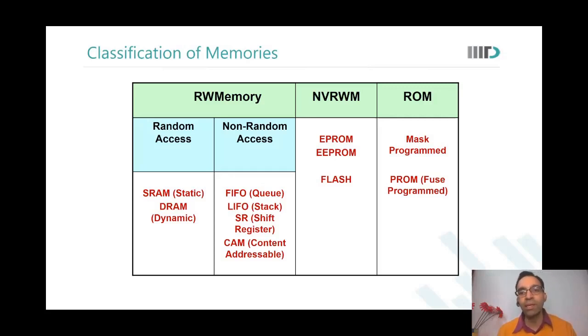This is the queuing mechanism which you would use for clock synchronization across two different domains. So how big a FIFO would you need? Sir, it can be application dependent. Yes, it is largely application dependent. It depends on the kind of variation in frequency, like what are the two different frequencies that you are merging, and also on how frequently you are expected to do this data transfer between two domains. If it so happens that you are transferring data in every cycle, then it can't really happen that we use a FIFO to take care of it.